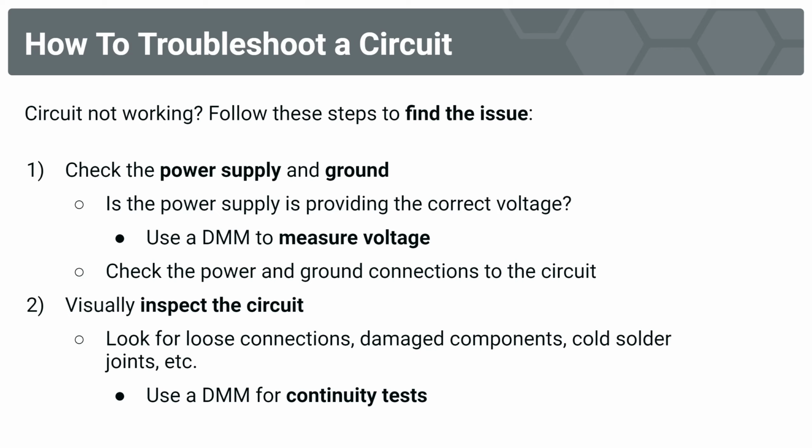Everything looks okay. You're going to visually inspect the circuit now. Look for loose connections, potentially damaged components. If you have soldered something to a perf board, look for cold solder joints, stuff like that. Things that are very easy to find via a quick scan of the circuit.